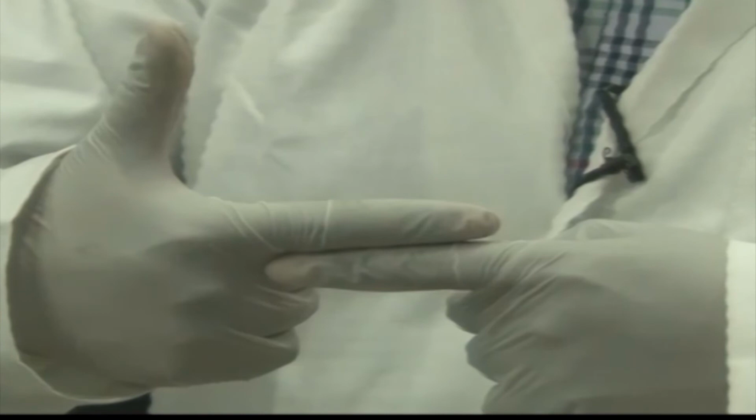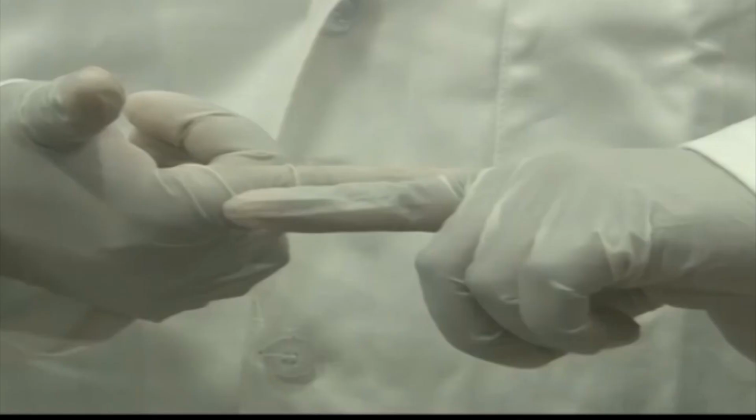What will happen? It will displace the nozzle. If this overlap is not here, this is 0.1 and this is 0.1, the nozzle will touch this one and it might displace the nozzle, the part might distort. So some overlap should be there, as there has to be some gap at this surface for the nozzle to work in. So for that, this overlap limit is given. This overlap limit can be 15% or 20%.